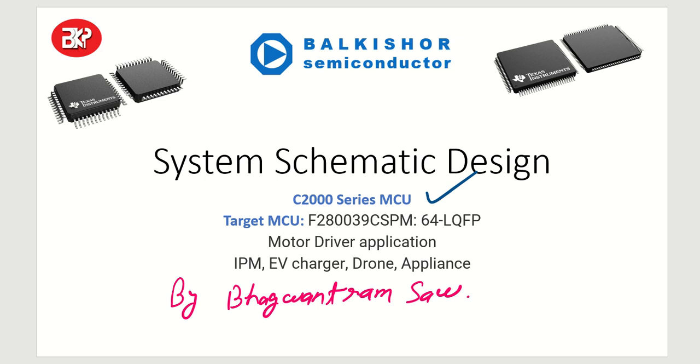So basically, in this microcontroller system design we are going to consider C2000 series microcontrollers, and my target MCU, as I told you, is the F280039CSPM, with the 64-pin LQFP package. As you already know, this series of microcontroller can be used for various applications in motor drivers, EV chargers, solar inverters, drone applications, or appliances like fridges and washing machines, wherever a motor application is needed.